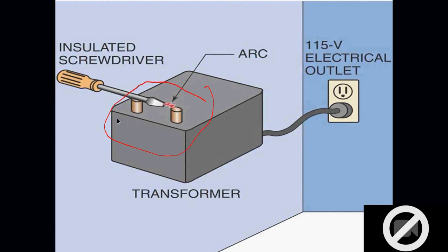Okay, you can also ohm out ignition transformers. If you unplug this, you take your ohm meter, go between the two pins of the secondary. Take a reading. You should have some number. Go between the two lines on your primary. You should have some number, other than 0. If it ohms out properly, your transformer is good.